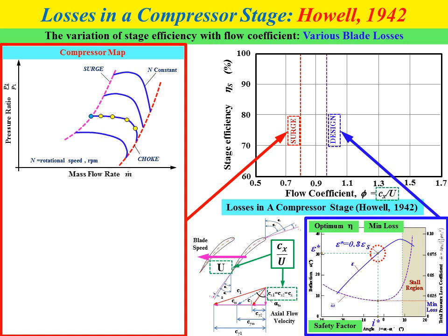So there is no effect on the pressure ratio if we change the mass flow rate. For normal condition, if we reduce mass flow rate, the pressure ratio of the compressor will increase. But at a certain point, the mass flow rate will not affect the pressure ratio obtained by the compressor. This point we refer to as the surge point.